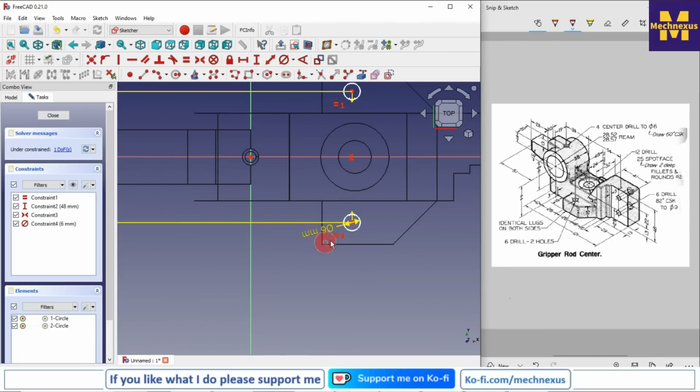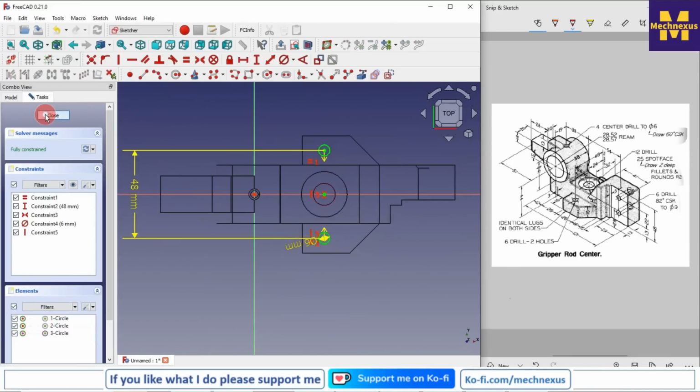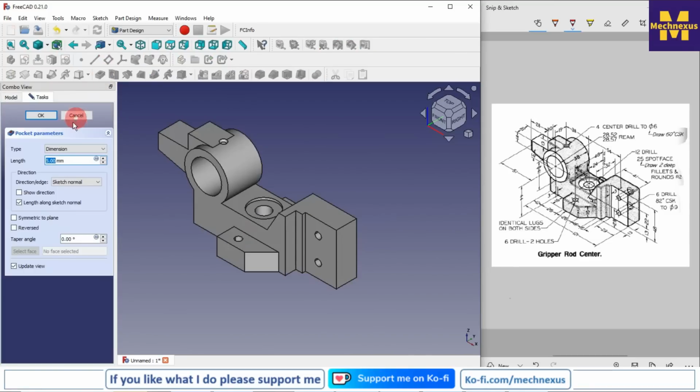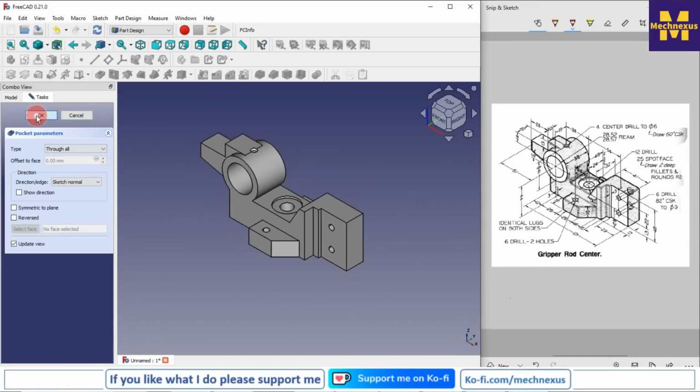And our sketch is unconstrained because it does not have the vertical relation with our this counter bore hole. So we will click on the project geometry so that we get a center. Now I will select these 2 points and I add a vertical relation and close it and switch to the flat lines. I will simply select the sketch and click on the pocket, and from drop down I will give the through all and say OK.